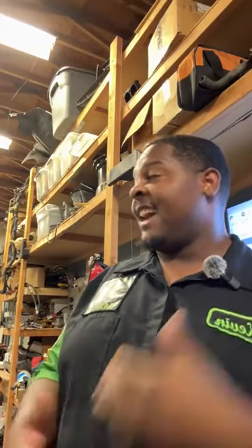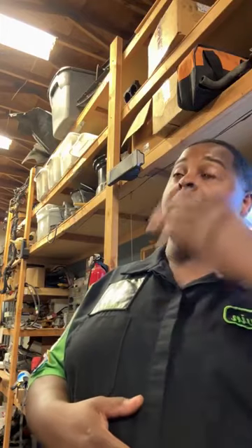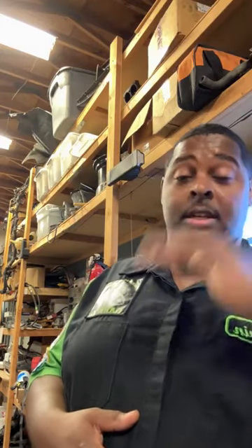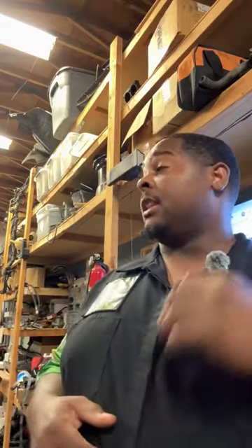I went for the cheapest option fuel pump. I think I bought it on eBay for like $30, whole assembly. And the fuel hose that they use between the pump and the actual tube that sends the fuel out to the engine was not fuel rated. Literally, I'm dead serious. It wasn't fuel rated. So I got all that out, put the new one in, put it all back together.